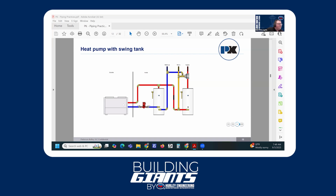And it's the same principle we have in heating systems that use boilers. If we have a system that has low mass and there's not much volume to it, we could have the same issues where we short cycle our boiler and our heating equipment. In that scenario, we'd use a buffer tank as a swing tank to add more capacity to our system.